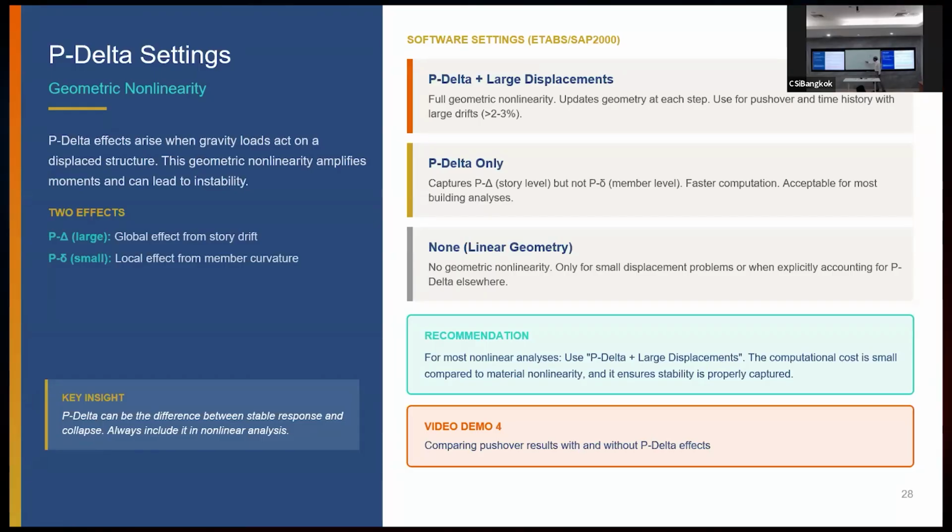Here it carried the load in compression, and now it is carrying the load in tension. So the stiffness will increase again. This is called a snap-through problem. That structure has a lot of stiffness, and then suddenly no stiffness, and again a lot of stiffness. So then drop here, and suddenly negative stiffness with negative deflection, negative load, you can say. So this will be a snap-through problem.